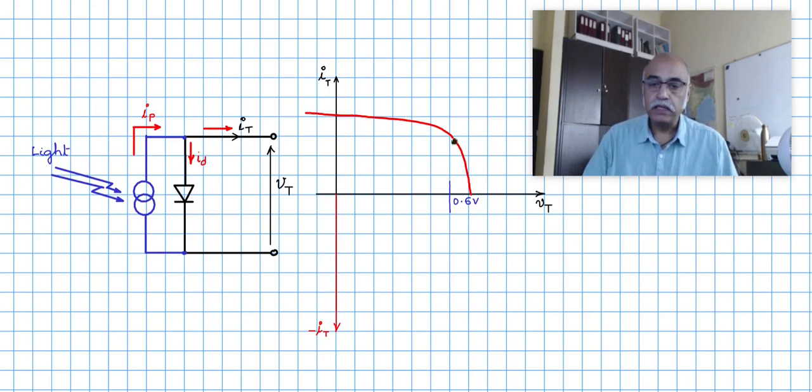Now you see the IV curve of the PV cell having some part of the characteristic which resembles a constant current, and there is some part of the characteristic which resembles a constant voltage, and therefore it is a combination of both constant voltage and constant current sources.